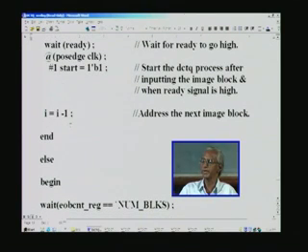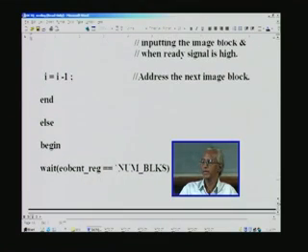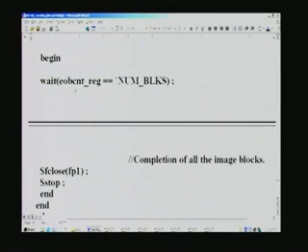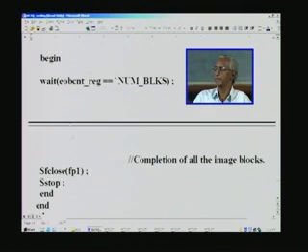That is why we are decrementing from 1024, then it becomes 1023 and so on, and finally it will become 0. When it becomes 0, it quits the always block we have seen before. In addition to this, we have a counter for counting the number of blocks processed, and then compare it with the number of blocks we gave right at the beginning, which is 1024. When the two are equal, this being the running counter, we stop and close the file, and that is what is here.